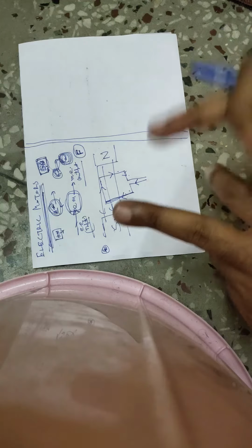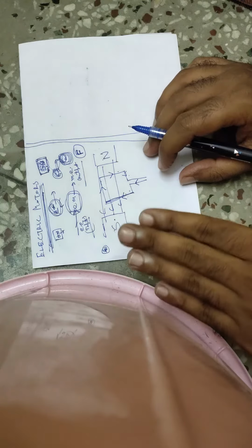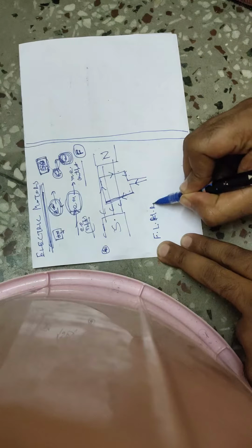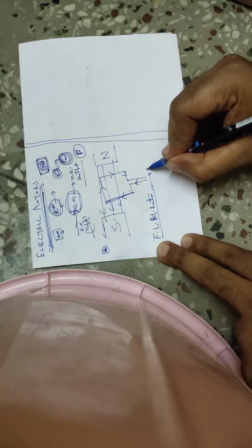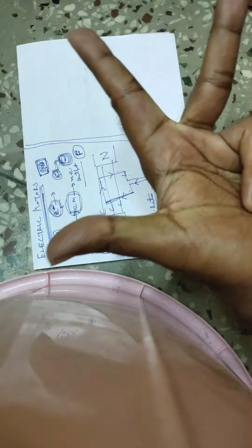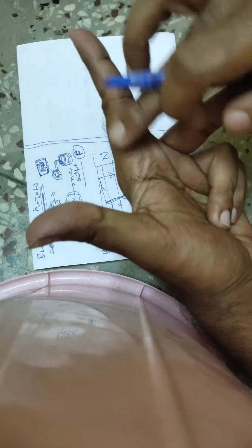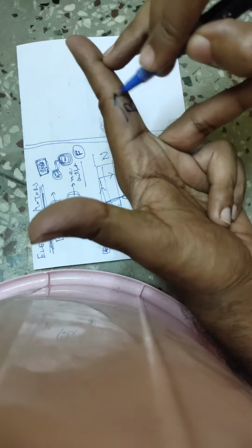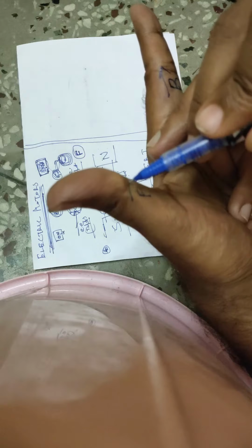Okay, so in the last lecture we also discussed Fleming's left hand rule. So what does this rule say? I hope you all remember the last lecture, FBI. If you put your left hand like this, with the fingers perpendicular to each other, then this forefinger will represent the direction of magnetic field. This will be in the direction of current. And the thumb will represent the direction in which the Lorentz force is being exerted. So FBI.